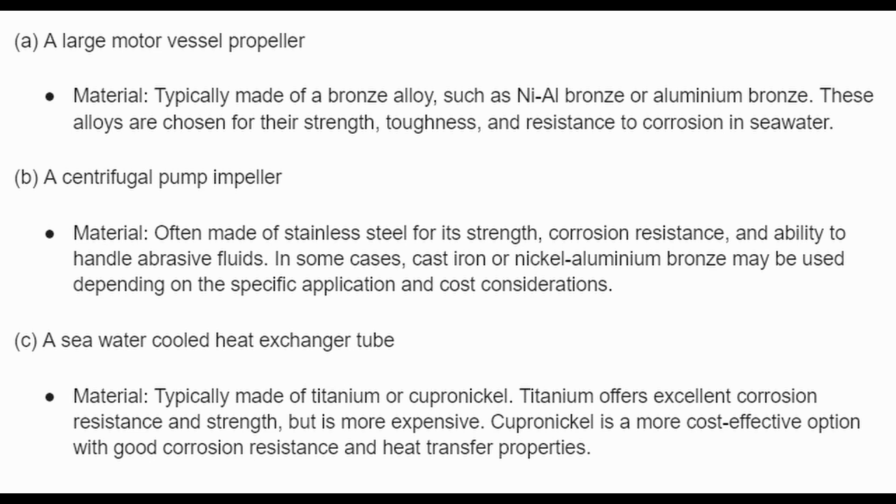C. A seawater cooled heat exchanger tube. Material: typically made of titanium or cupronickel. Titanium offers excellent corrosion resistance and strength, but is more expensive. Cupronickel is a more cost-effective option with good corrosion resistance and heat transfer properties.